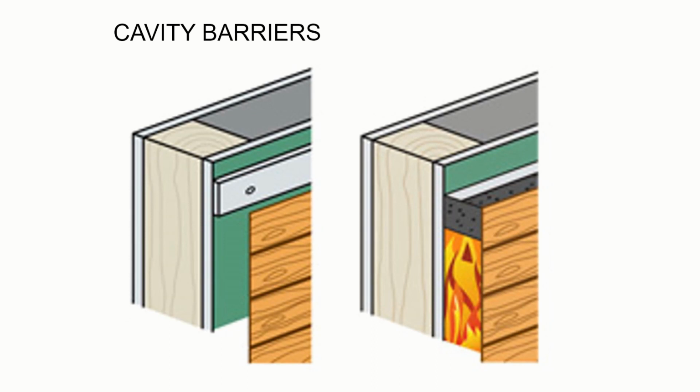For timber, it's important to be able to keep the airflow behind the timber going all the time, so we can't always just block off the cavity. So we use an intumescent material, which expands under fire. When it gets hot and charred, it reacts with the heat, expands out, and becomes an impenetrable fireproof foam.